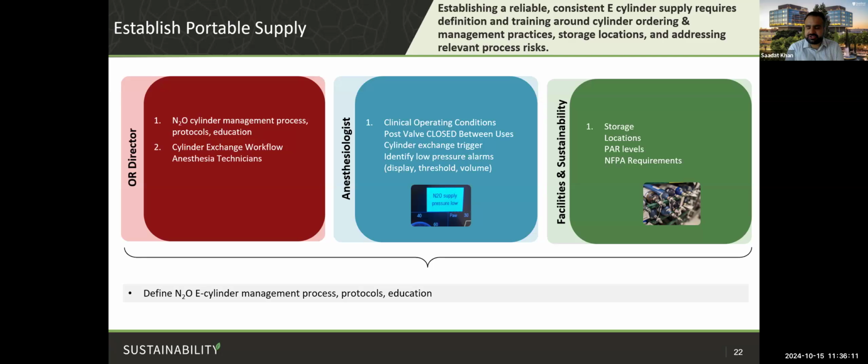They must be designated as such. And then we worked with our anesthesiologists and the biomed team, especially in making sure that the low pressure alarms on the anesthesia machines have working displays and have the threshold and the volume defined, so that if we are ever at a point where our nitrous supply is running low, we know with ample time to actually replace the e-cylinders.